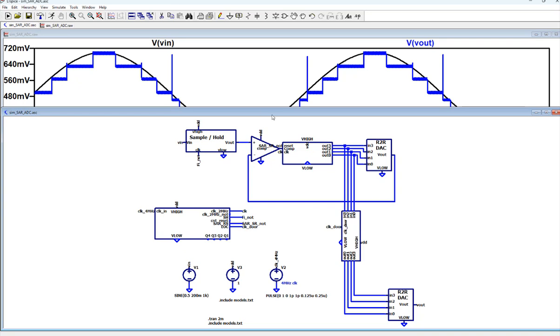That's fine. So I'm going to provide you with this design. You can look at the sizes, and if you are using 180, so 180 also accepts 1 volt, but we are probably going to use 3.3 volts for VDD. So just resize all the transistors by a certain ratio, make them a little bit bigger. As long as the logic works, it should be fine. So the only thing you need to modify is whenever you see some of the outputs becoming weird, not able to charge up, and then starting to oscillate, which means your output doesn't have that driving capability.